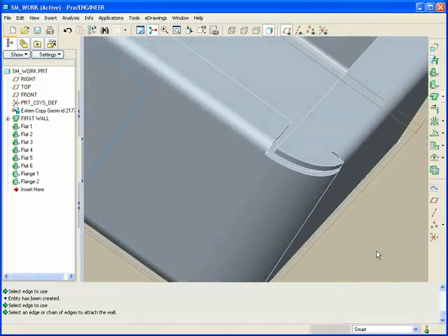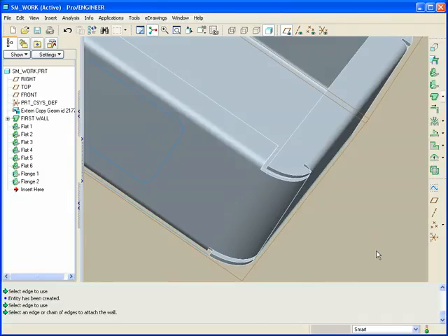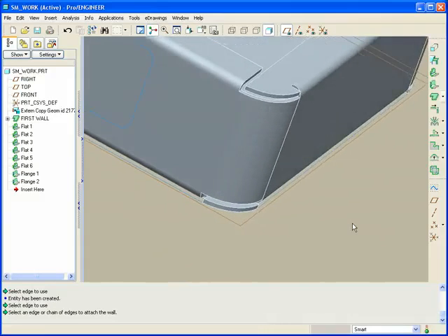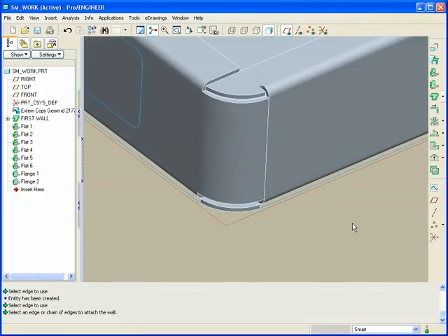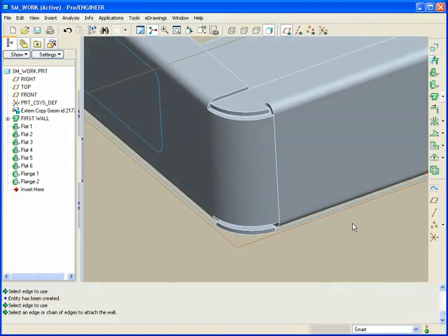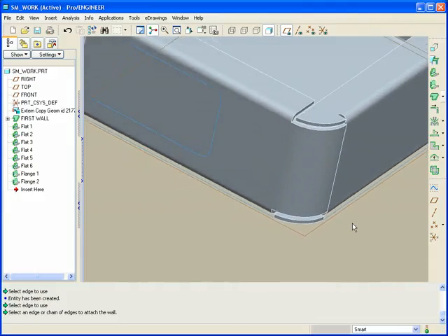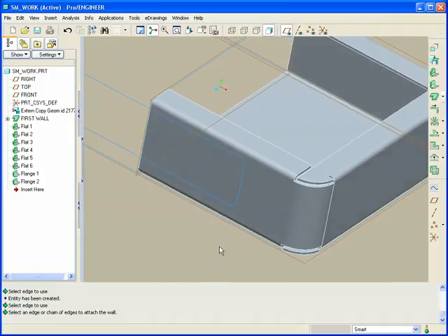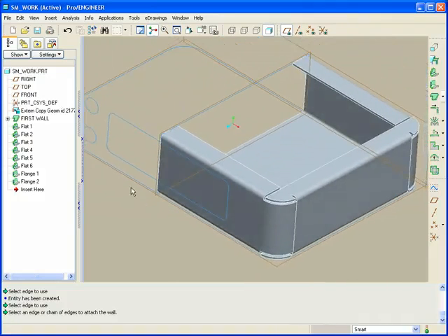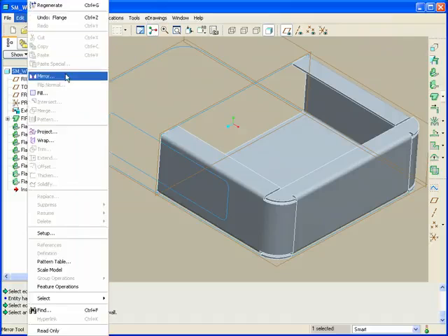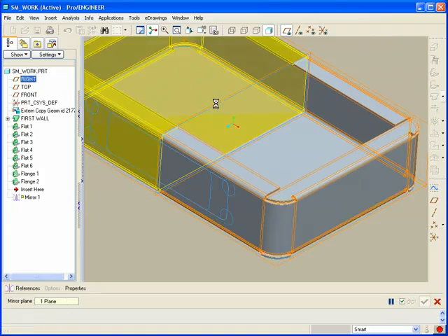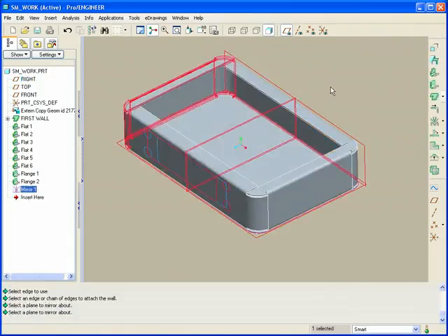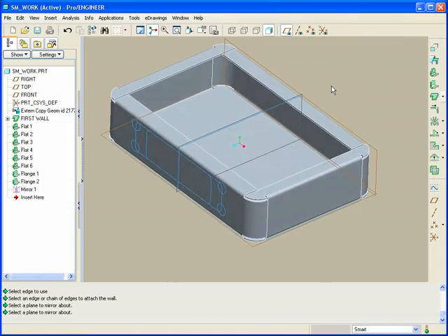Of course, if you wanted to close that up, you certainly could with just changing the way you did the sketch here. You might want to make those rips, those reliefs a little bit different. Number of different options. All of them are doable. Now, if I want to mirror this to the other side, the way that works is you pick the top of the model tree, edit, and mirror, picking then the middle plane. Middle mouse, and that gives you a very nice mirror geometry without a whole lot of references.